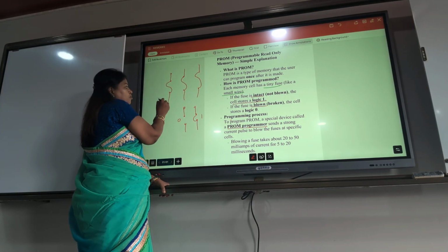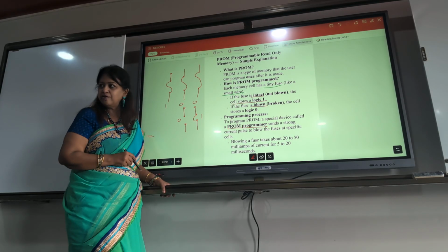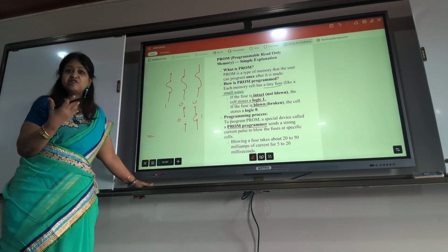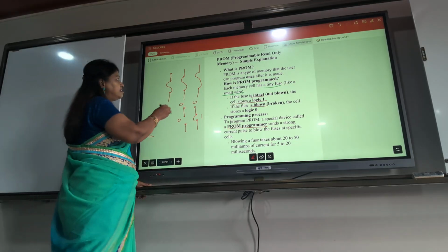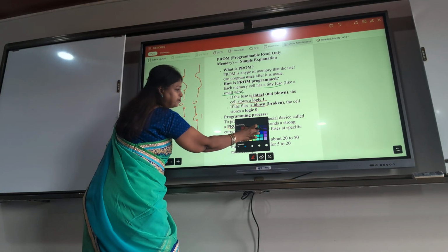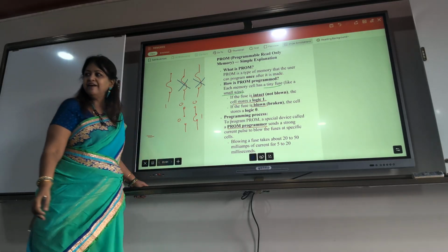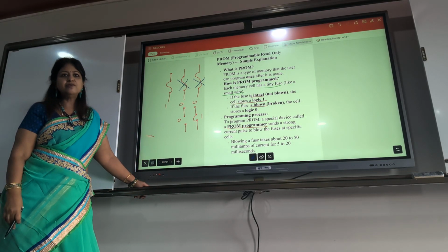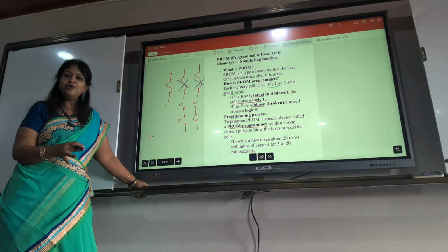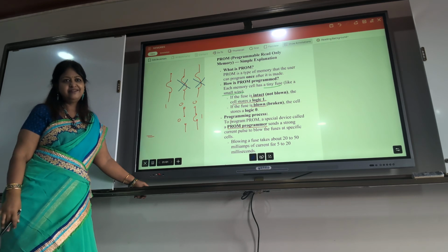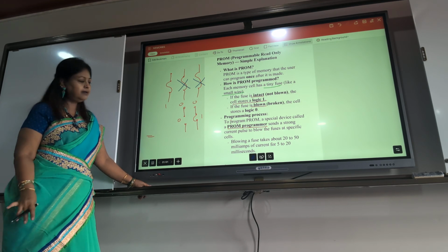I want 100 to be stored. What will I do? I have to send strong current to all these lines and blow the ones I don't want. When I blow the fuse, I'll get 1, 0, 0. Once I finish doing that, I can't change it. With PROM, I can blow only once.